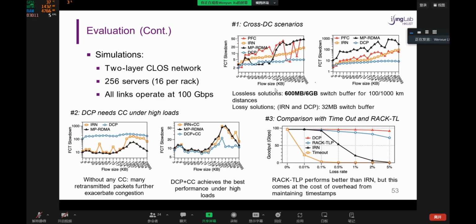Okay, I think for me personally, the most difficult part is to understand the current RDMA NIC architecture and its ASIC implementation, and to fit the DCP needs to the current implementation without very significant modification overhead, and finally to really implement the DCP design using the FPGA and the Verilog language.